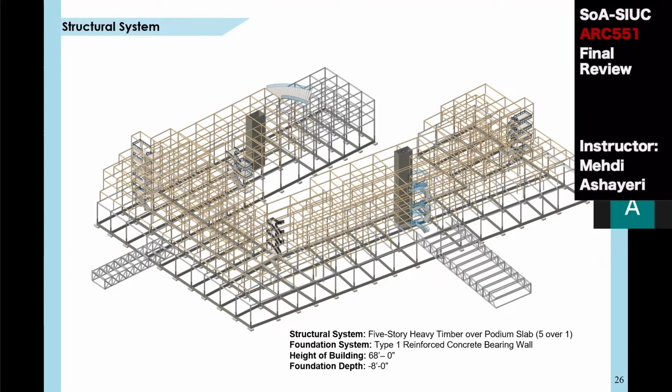There's also a 3-hour fire rating between the bottom level and the upper residential levels, so that gives a little bit extra protection. They do require a different sprinkler system, so they have to have an NFPA 13 sprinkler system installed in these buildings. This is becoming a more common form of construction because it is actually a cheaper alternative to an all-steel building. It also is more eco-friendly, believe it or not.